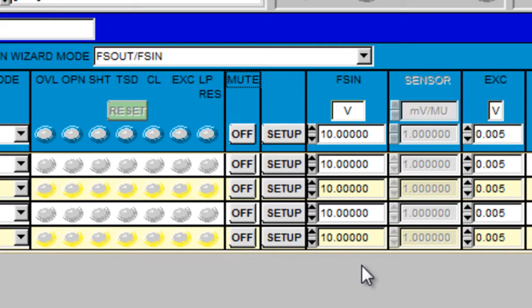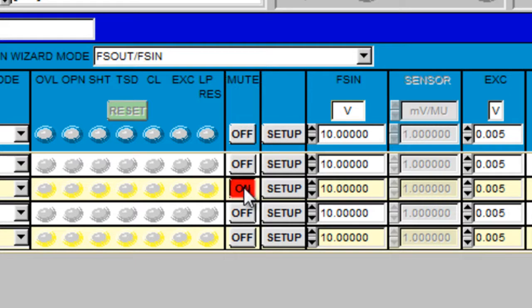The problem channel or sensor can be put into a state that turns off power to the circuit by disabling the excitation, disconnects the amplifier from the sensor, and puts the channel into a low gain and low bandwidth state to limit the possibility of noise propagating through to other channels. Once the fault condition has been addressed, unmuting the channel restores all of the previous settings.